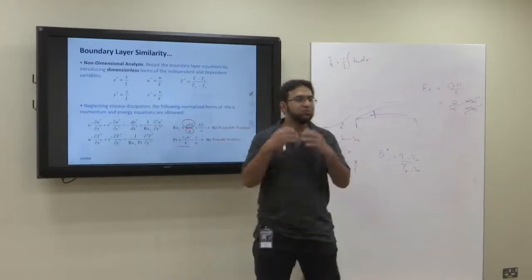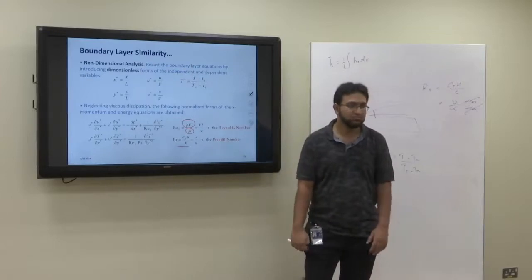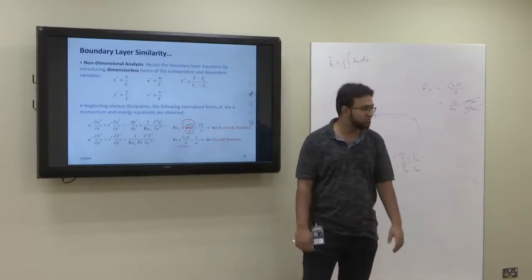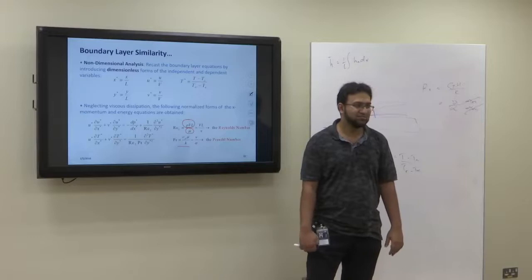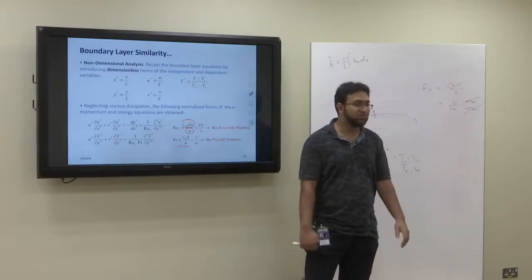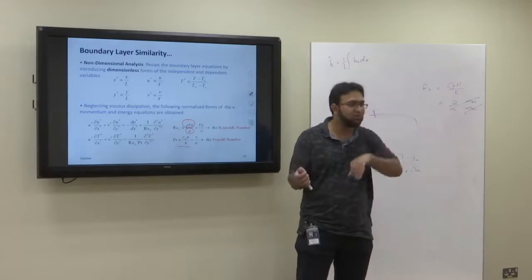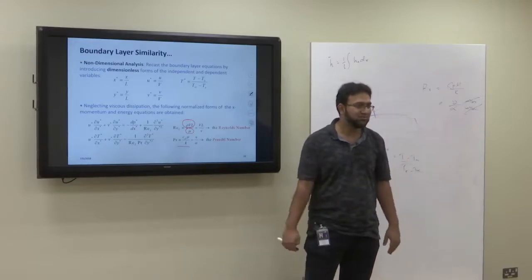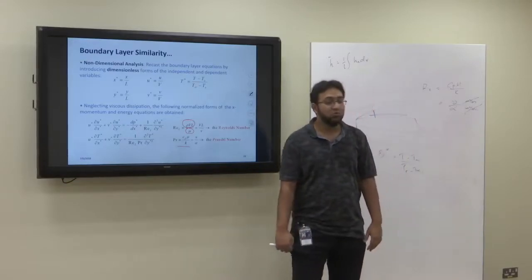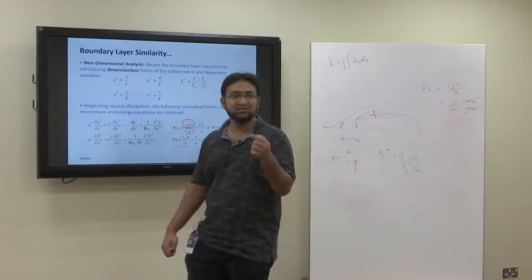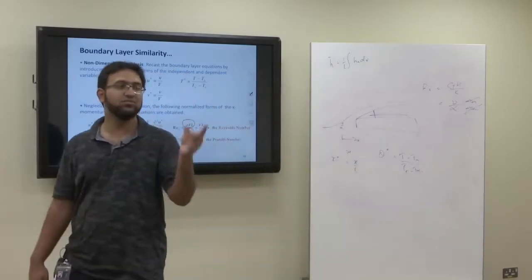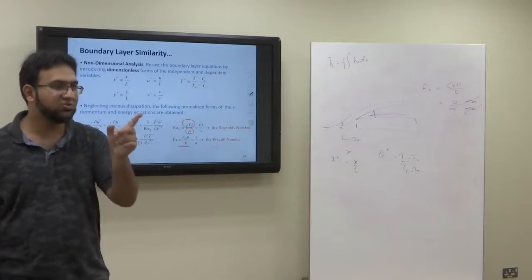Reynolds number is the ratio of 2 forces. Biot number is the ratio of 2 resistances. Fourier number is the ratio of 2 heat energies, energy conducted over energy stored per unit time. Okay. Which parameter is the ratio of what thing is important from the short questions point of view?